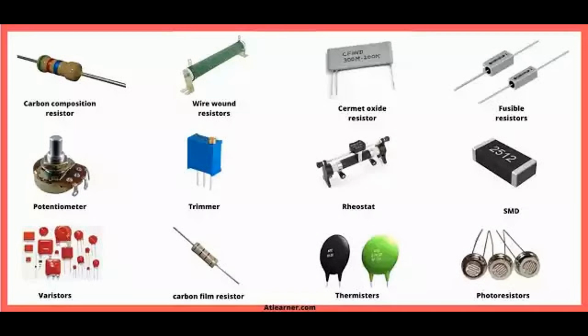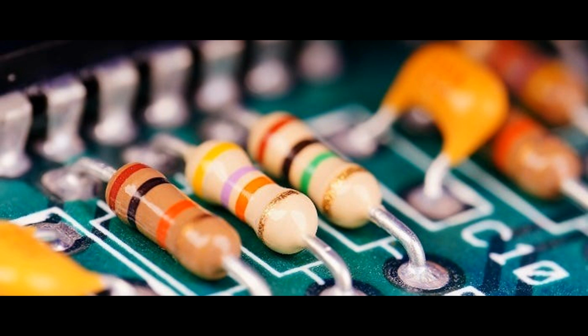Choosing components with lower power dissipation, such as low R_DS(on) MOSFETs, can reduce heat generation. Derating. Operating components below their maximum rated voltage and current to reduce power dissipation and extend their lifespan. Power distribution. Distributing power across multiple components to prevent excessive heat in any single component. Packaging and enclosure design. Ventilation. Designing enclosures with vents or fans to allow for adequate airflow, preventing heat buildup.